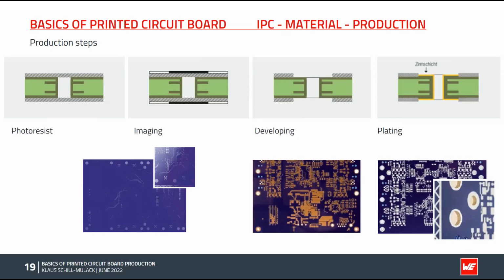In the plating process, which follows, the through-hole traces and all copper surfaces are copper plated to the required thickness. Finally, the copper is protected with a tin layer. This means now the resist is no more the film, the resist is the tin layer.